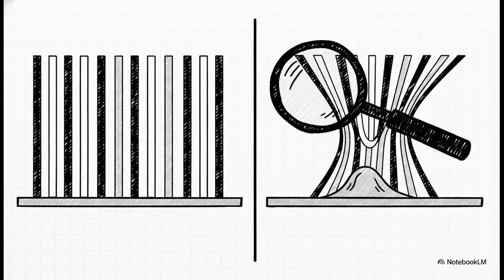And this fringe counting technique isn't just a neat lab trick, it is entirely vital for modern manufacturing. Industry relies heavily on wedge interference to test surface flatness for microscopic defects. If the fringes are perfectly straight and parallel, the surface is flat. If the fringes warp even slightly, you've got a defect. This exact same principle is used to check the quality of camera lenses, telescope mirrors, and glass prisms. It allows engineers to achieve precision measurements with literal sub-nanometer resolution.